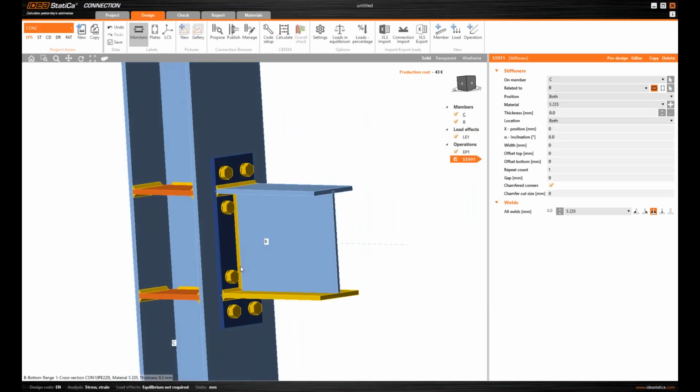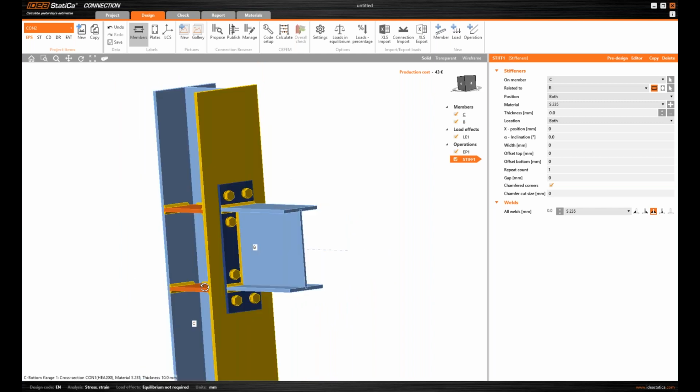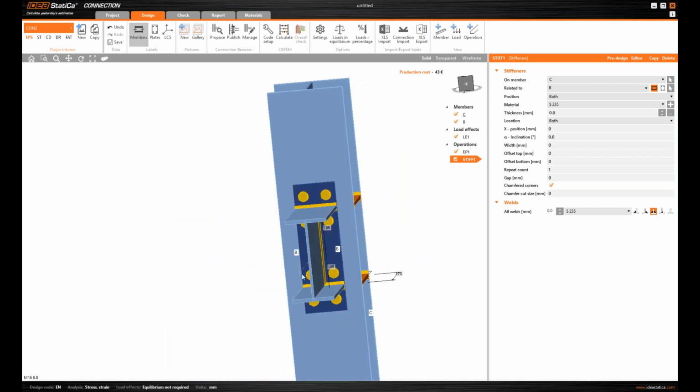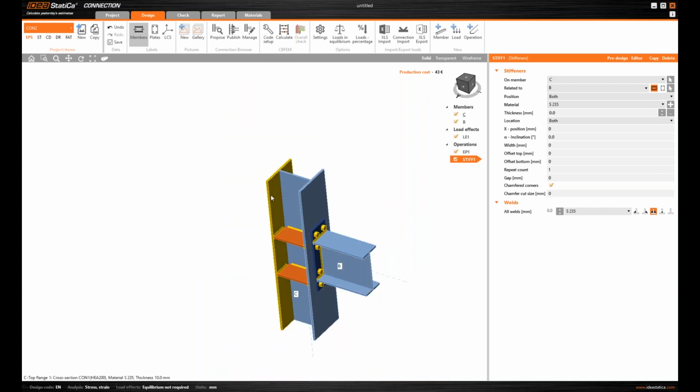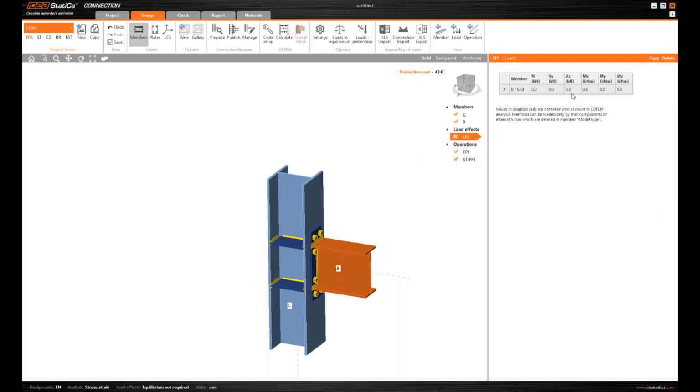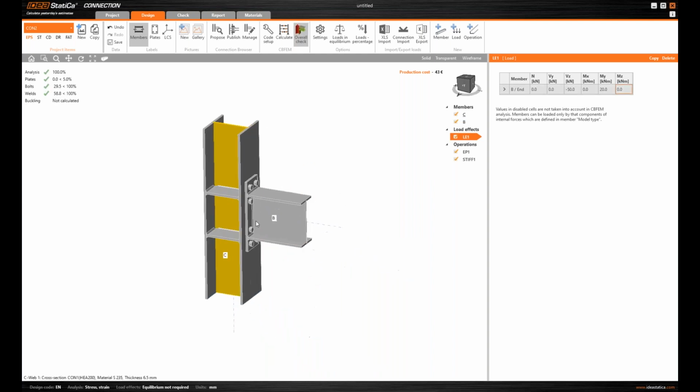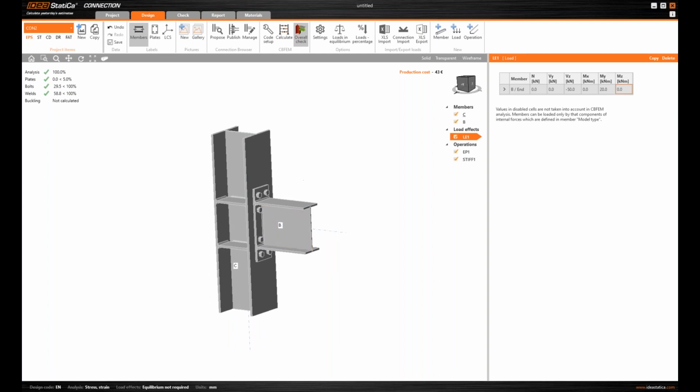Okay, yeah, type or size of the bolts here. Yes, I'm quite there, and everything I need to do is just check if the sizes are according to my expectations or not, and check the forces. So again, we could make it slightly bigger, so maybe 50 in shear force. What about 20 in bending moment? Okay, does it still work? Yes, it does. Okay, it's there.